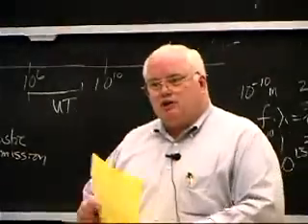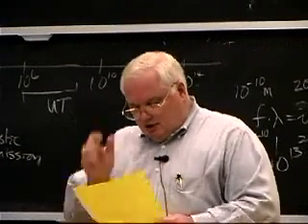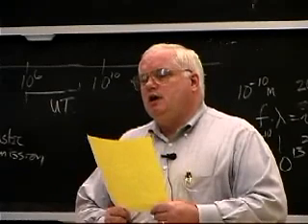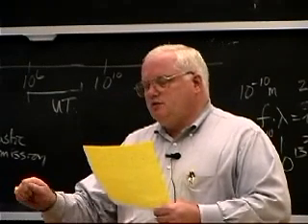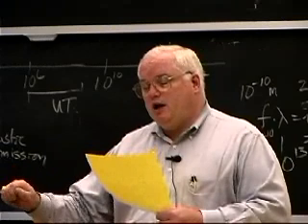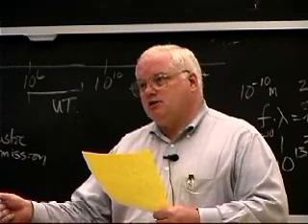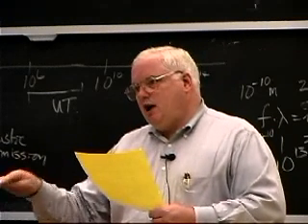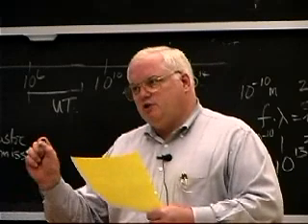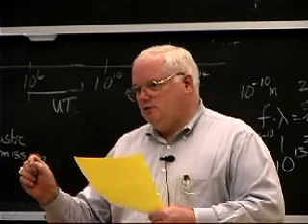You can't really get smaller at 1,000,000 hertz. Most ultrasonic machines will have typical frequencies of 2.25, I don't know why they came up with that, up to 10 megahertz that you can test. You get more attenuation at the higher frequencies, so your signal to noise ratio goes down, but the size of the flaw that you can detect is smaller.